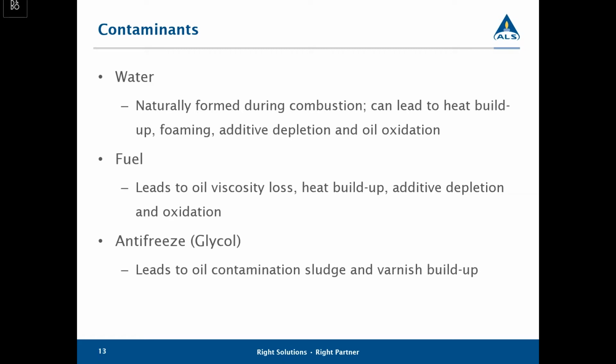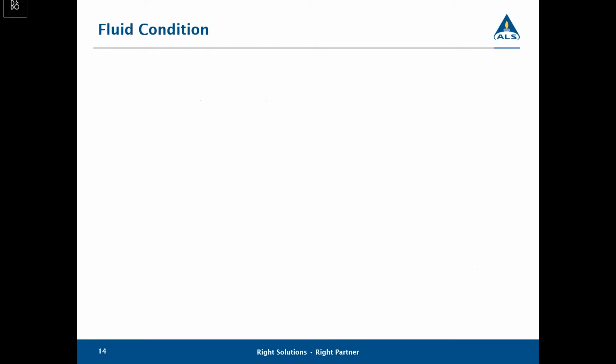Antifreeze, a lot of engines could be water cooled, but those that may be using an antifreeze, if it does get into the oil, that glycol really does not like to mix with oil, and it will cause a sludge to occur and varnish. And so it's something that you really want to identify as quickly as possible, and that can be determined fairly quickly through the multi-element determination. Depending on what kind of antifreeze it is, you'll see sodium, potassium as some of the main elements present in those.